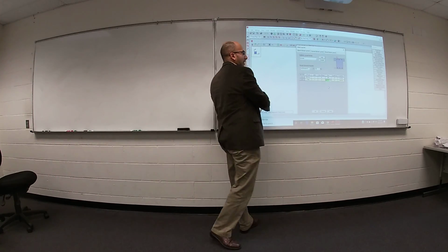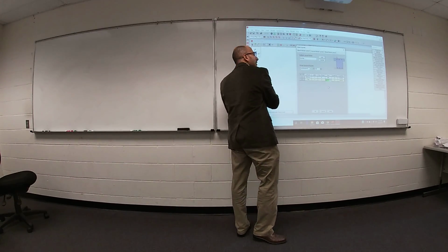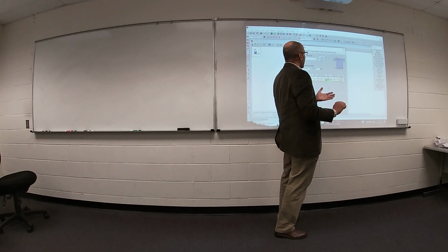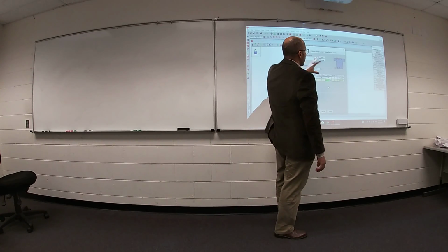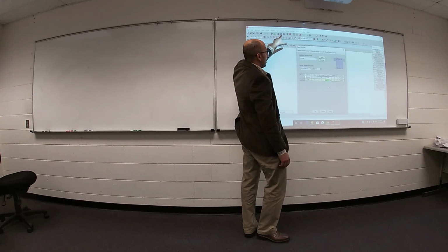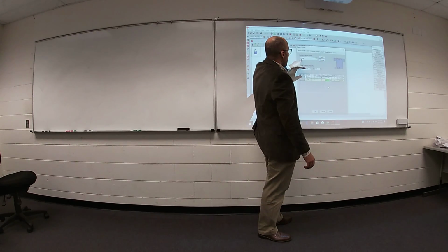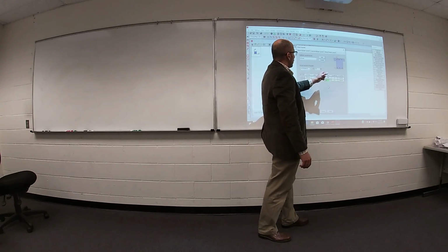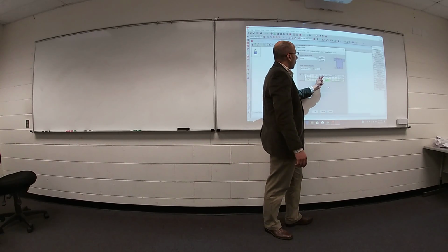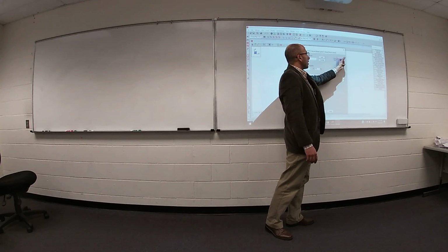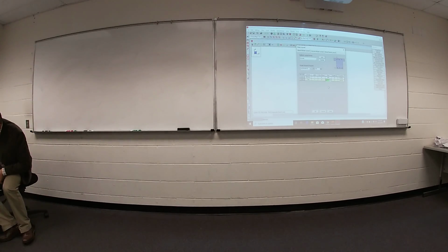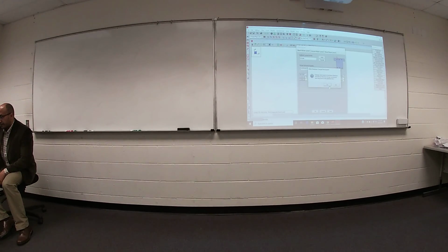If you would like to make your design here, fine, but I prefer to make the analysis only, and make the design with hand calculation. Anyway, if you would like to define steel reinforcement from this icon, add, put your name, and then define how many bars at the bottom, the size of each bar, how many bars at the top, and the size of each bar. Once you hit OK, then insert beams.